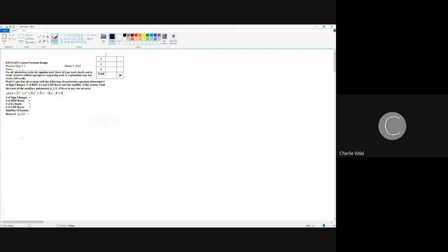So to start this problem off, we're always going to make the first 2 S's. So we're going to go like S5 and S4. The reason I'm only doing the first 2 is because if you put down S3, S2, S1, S0, you might have to erase your rows because you could get a row of zeros. And if that happens, it's just a waste of time. So just put S5 and S4, or the first two S's that you see.